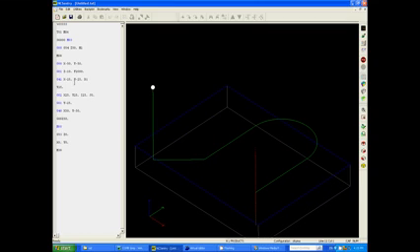The reason is we call on cutter radius compensation later, and what you need to do is move to a distance suitably away in the two axes that you're calling radius compensation on, to allow the machine to adjust the cutter position automatically. So instead of being on the spindle center line like it will be here, as it moves to this point with cutter radius compensation on, it will automatically adjust using one of two codes, which I'll talk about in a minute.